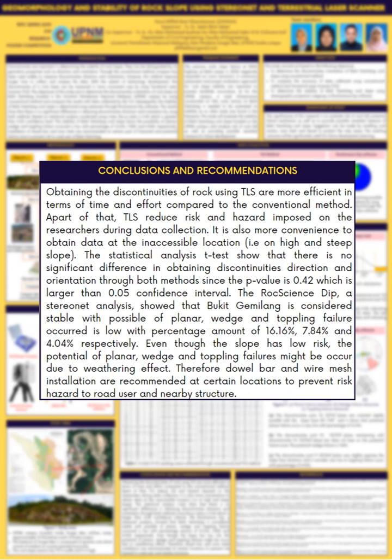The RocScience Dips Stereonet analysis showed that Bukit Gemilang is considered stable. Even though the slope has low risk, the potential of planar, wedge and toppling failure might occur due to weathering effect. Therefore, dowel bar and wire mesh installation are recommended at certain locations to prevent risk hazard to road users and nearby structures.